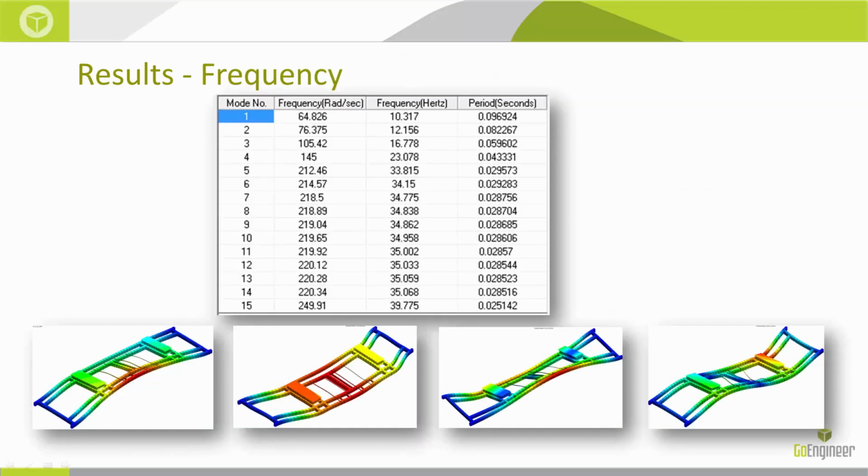So now let's look at the effects of the pumps. In order to do that, we're going to run a linear dynamic simulation, which has a frequency study embedded inside of it. With the frequency study, we have the same loading conditions, but now instead of stress and displacement, we get the resonance of our model, so what frequencies excite the geometry, as well as their mode shapes. And what we do in the linear dynamic study is include as many of these mode shapes as needed to accurately characterize all the possible movement of the structure. This also encompasses the full operating zone of our pumps and motors.